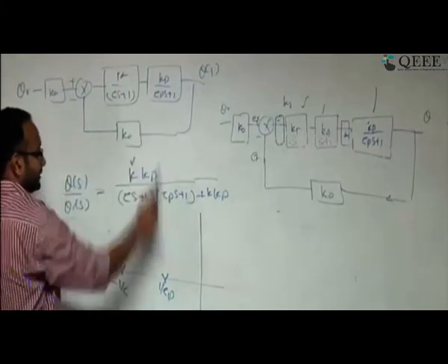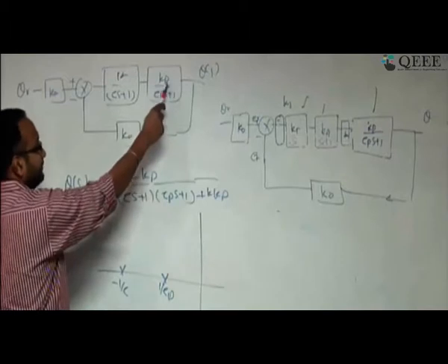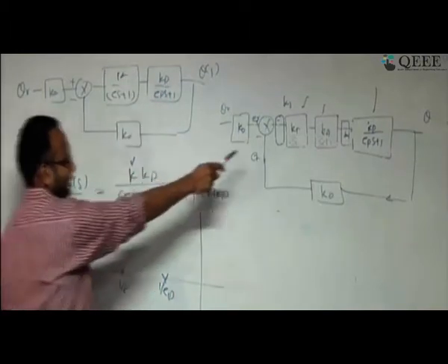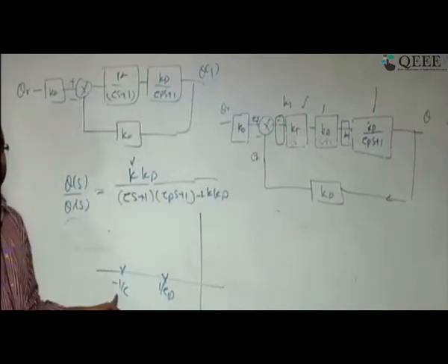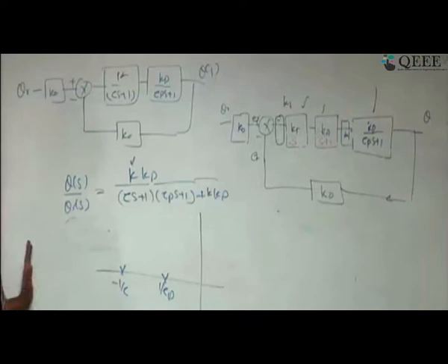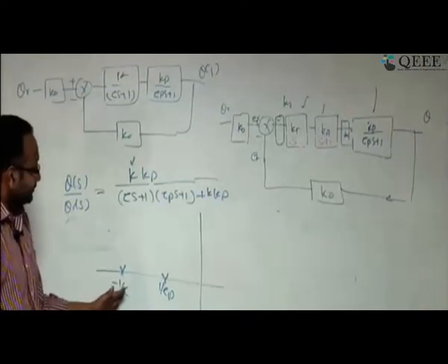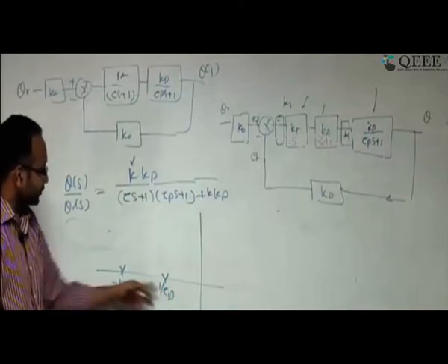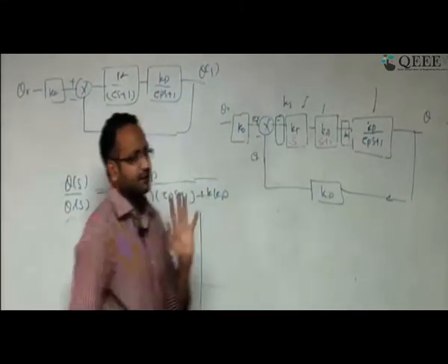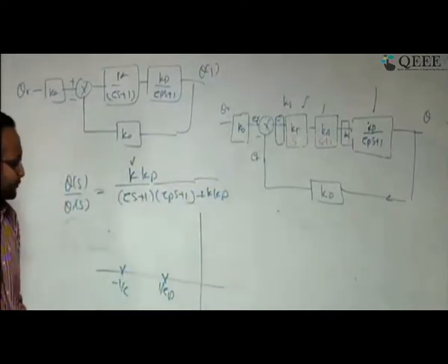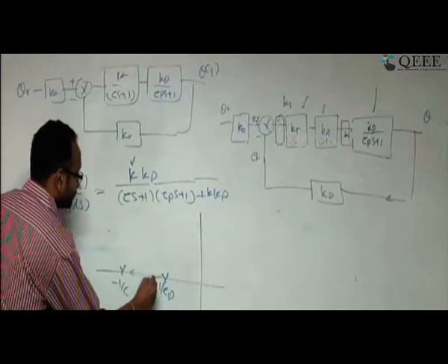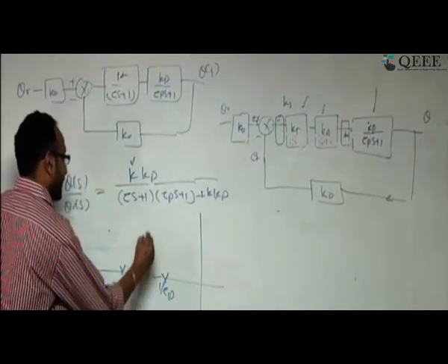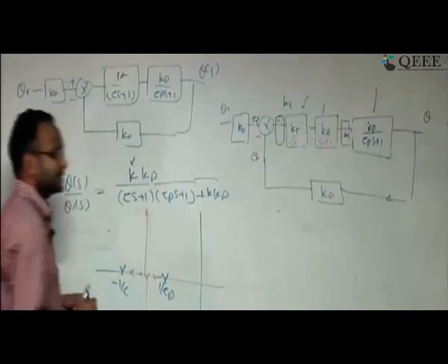Okay. What it says is that this is the pole location of the system, and this is the pole location of this component. And here I am keeping it purposely. It says that if I move away from the system pole, then my system is faster. So this system is slower than this component, and it's a reasonable assumption. Now if I keep increasing k, what happens? These two poles will come and they depart. This is asymptotic behavior.